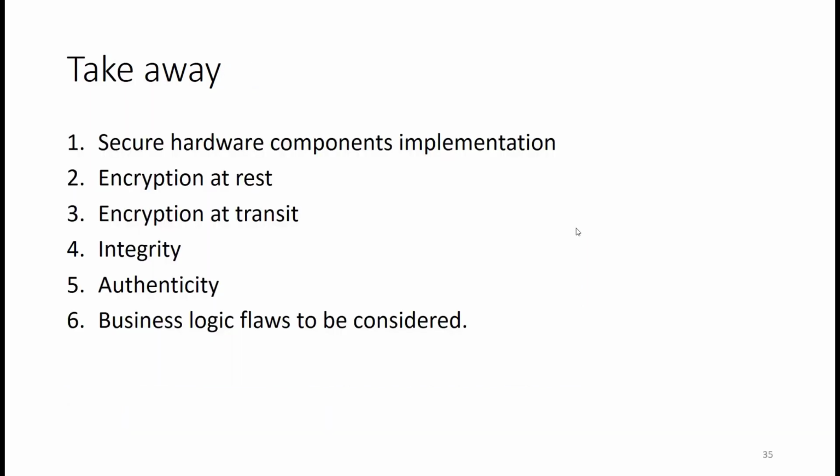So that was a very brief introduction about hardware breaking of any IoT or embedded device. And as an outcome of all the things we have discussed in this session, we need to have secure hardware component implementations, like readout protection, obfuscation, encryption, and certificate exchange to secure the binaries and the data in the device.